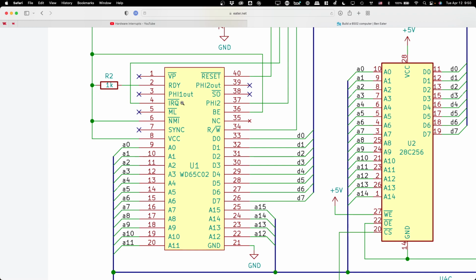Now, in the case of games like Mario, there is also another way you could do it, which is you could poll the controller very, very frequently. For example, every horizontal scan line or every frame of video, you could check to see whether or not buttons are being pressed. Probably not a very efficient way to go, but in some games where you're expecting button presses to be happening all the time anyway, that might actually be more efficient than doing the interrupt method.